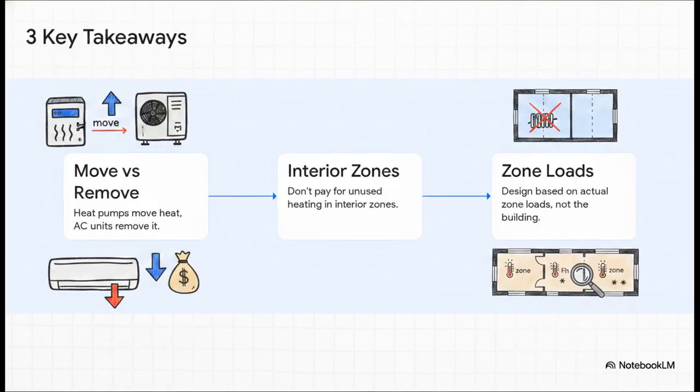Okay, before you go make your next big HVAC decision, I want you to remember these 3 key takeaways. First up, heat pumps move heat, while AC units strictly remove it. Number 2, please stop blowing your budget by paying for heating equipment in interior zones that will literally never use it. And third, always design based on the actual zone loads, not just broad assumptions about the whole building.